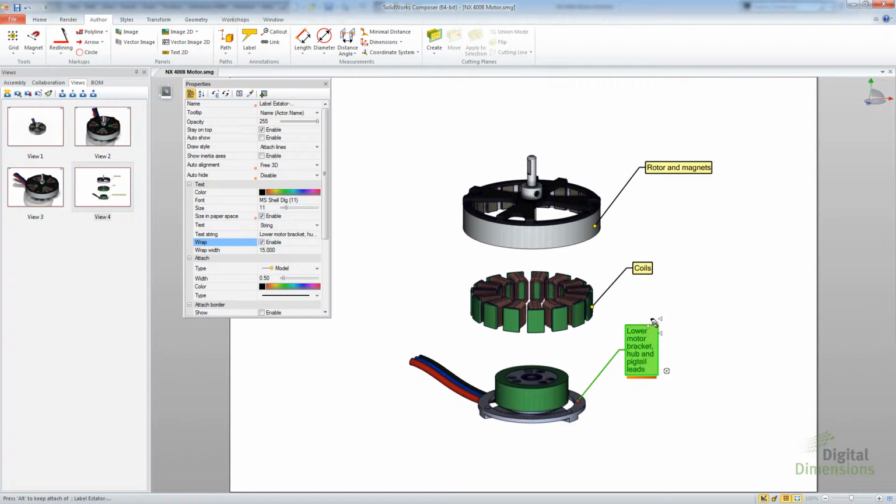Or you'll notice that there is a new handle in the upper corner there that I can actually drag and allow it to auto wrap there. So I can actually set this. You can also store this in the styles, so I could say I want all mine to only be 40, and then it'll force that to stay consistent throughout all my labels that I create with a particular style there.